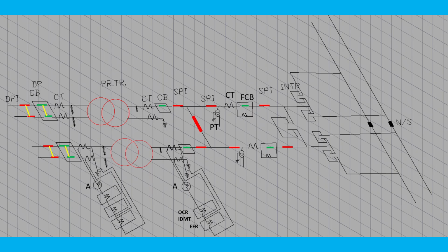Why are you using CT and PT at this voltage and current? Because we have to work manually with humans. A man will operate all these things, operate the panel board, so he should be in a safe condition. So we have used these instrument transformers, the CT and PT, to protect our operator. Otherwise, you cannot operate this huge power. So we are using a control circuit for the panel board. It is 110 volt DC.